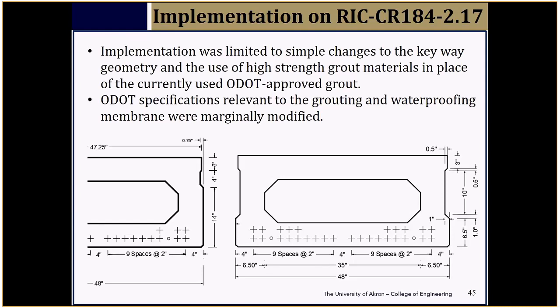We can imagine box beams arranged side by side, and imagine holding the box beams at the top. The beams can rotate and they are unstable because the contact that the keyway joint is giving is only a small amount. So it can truly rotate about the joint.